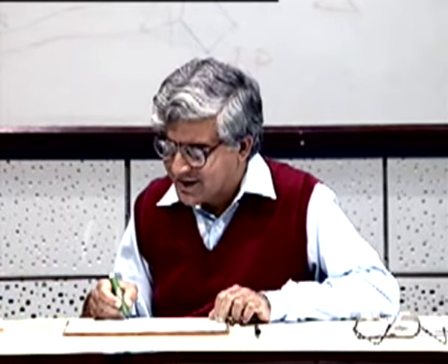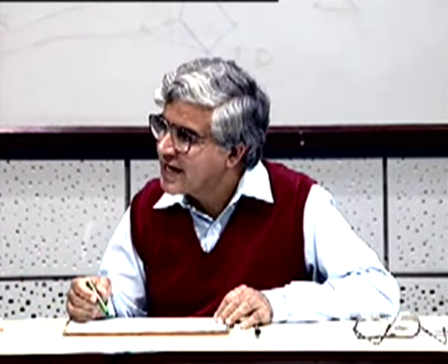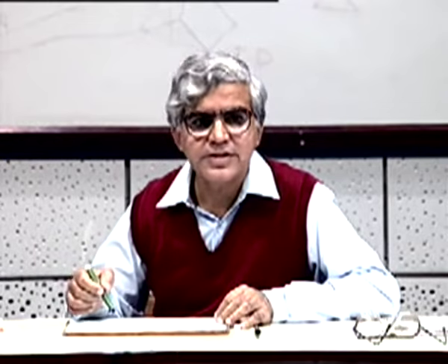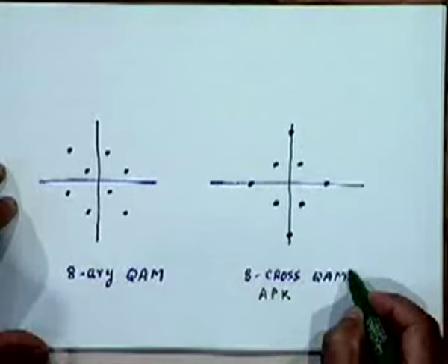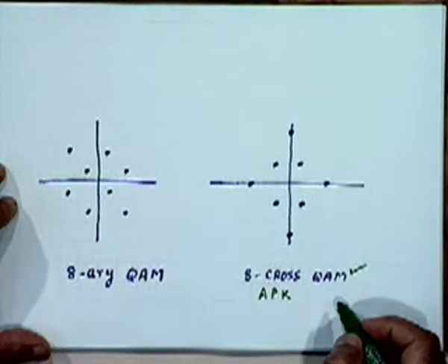You can see each of these names makes sense because in these schemes, from one representation to another, both amplitude and phase are being varied, whereas in a pure PSK only phase is being varied, just to distinguish these from the pure PSK kind of modulations, right? But the most common name today is QAM. So if you remember that, it's fine, right?